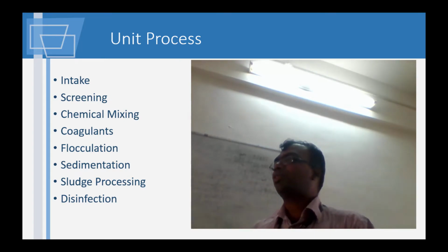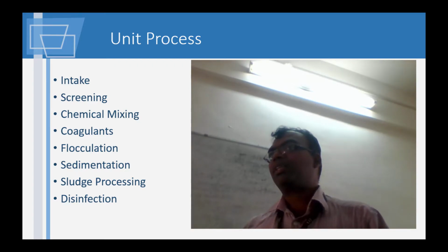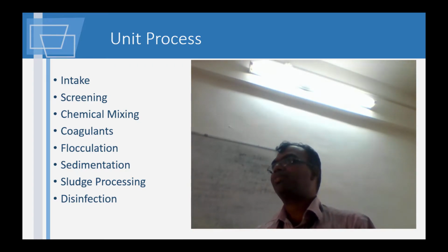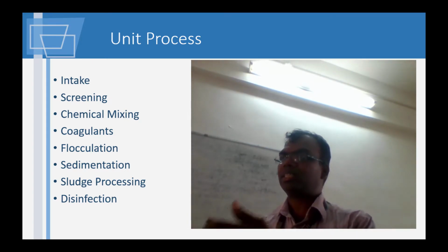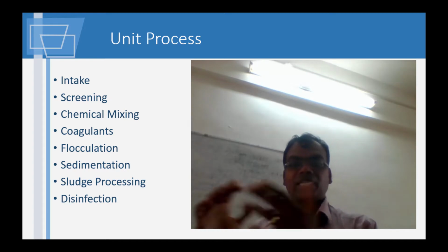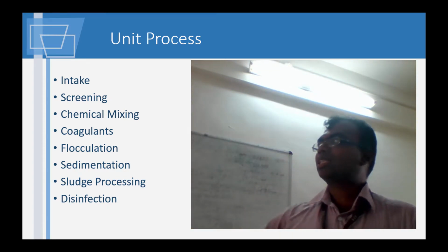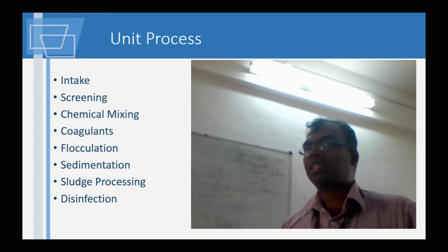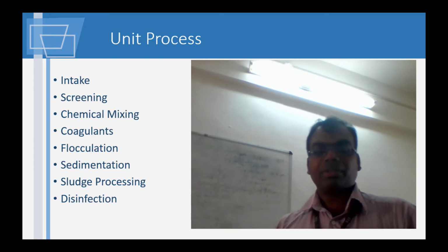Normally, if you look at your sewage drain, the water will turn black only after a couple of days. Essentially, nutrients attract surfaces on which absorption of the bad things takes place, and slowly the oxygen level comes down. So basically they try to increase the oxygen level.